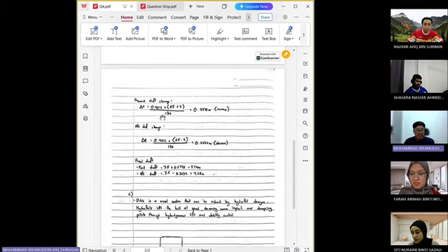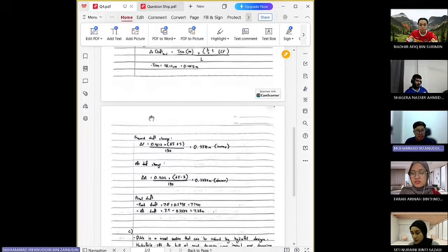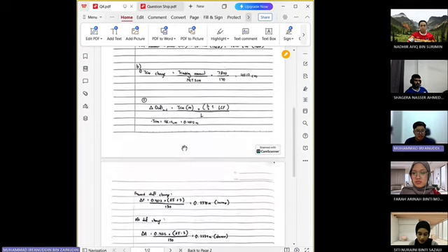And for the forward draft change, you take the trim with the new unit, which is 0.4612 meters, times 65 plus 2 LCF draft.